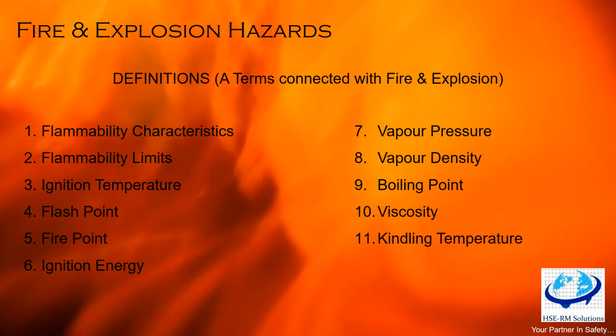So that is called lower explosive limit. While above a certain concentration, the upper flammable limit, it is too rich, and is also called the upper explosive limit, that is UEL, correct? So the definitions and the terms you must understand. What is UEL, what is LEL? These are the two terms that are normally used when we are talking about fire and explosion.